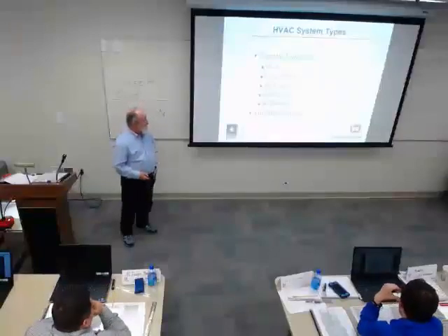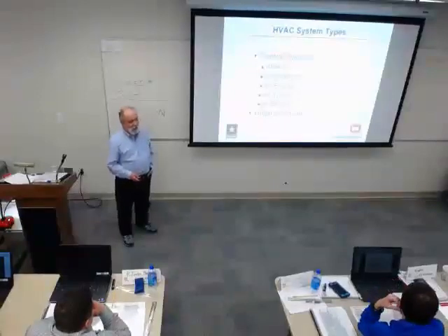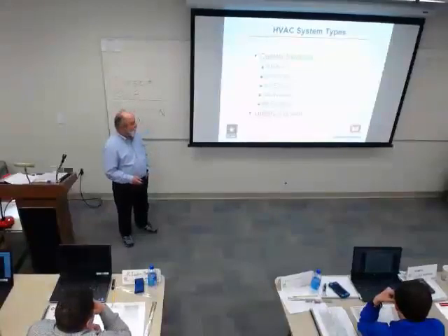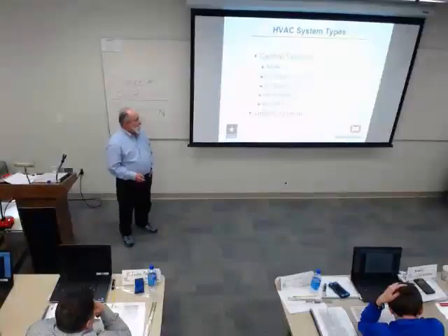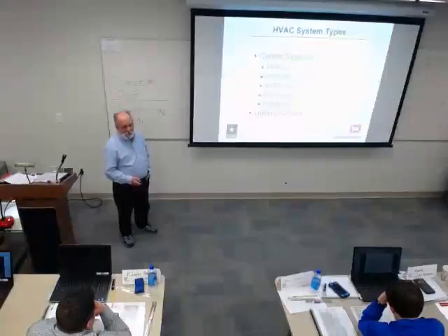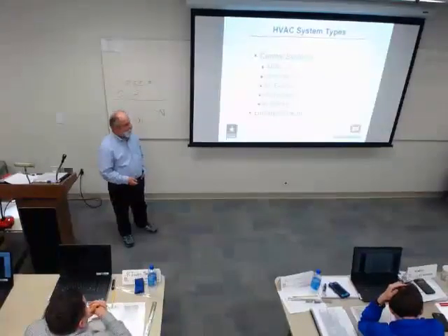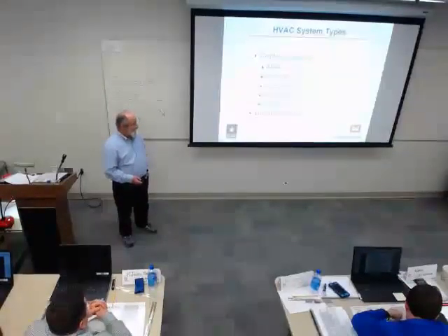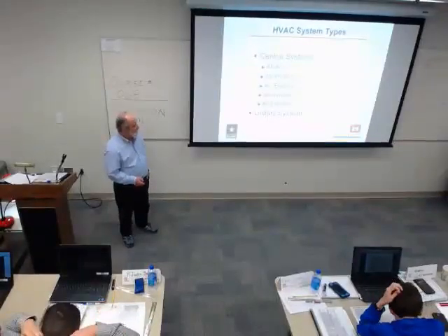We have central systems, where you start with an all-air system. I think of the ventilation we do for mechanical rooms very often, just a fan and moving air. Sometimes we have duct with the fan, but basically there's just air. Then we have air-hydronic, where air transfers its heat to the hydronic system or picks up heat from the hydronic system. We have air-electric, in which the heating element is electric. We have all-hydronic, and then all-electric, and finally the unitary systems. The unitary systems we'll talk about in more detail, and you'll see what that's all about.